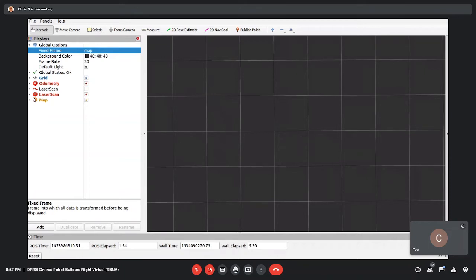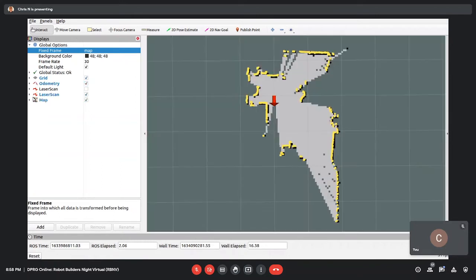So I'm going to kick that off, and then I'm going to kick off at the same time, okay. So I kicked off in a different window the playback of the recorded data, and I kicked off the mapping/localization program called Gmapping, and another program was already running that's filtering out the distorted laser scans, and we'll see that in action in a second.